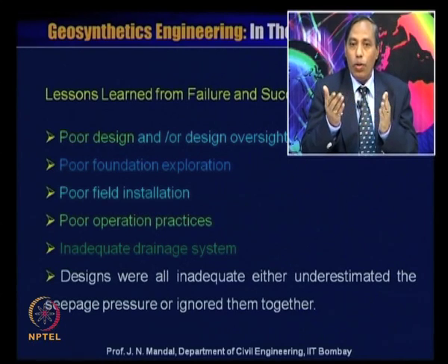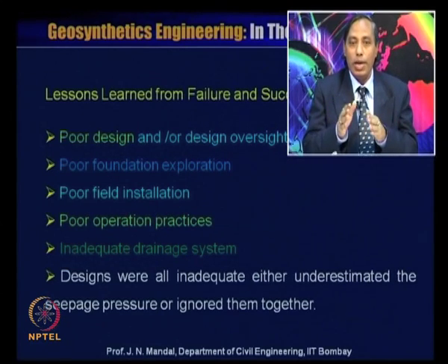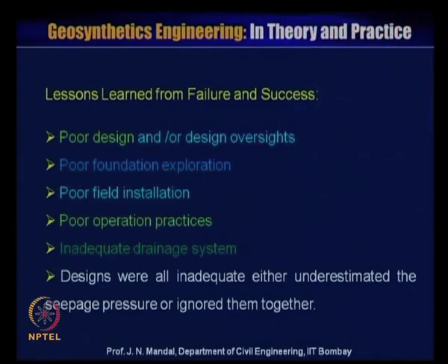Designs were inadequate. They underestimate the seepage pressure or ignore it altogether. They sometimes do not consider the seepage pressure which occurs at the back of the reinforced soil retaining wall or the slope. So, that should be taken into consideration in the design, otherwise most of the time the structure collapses.